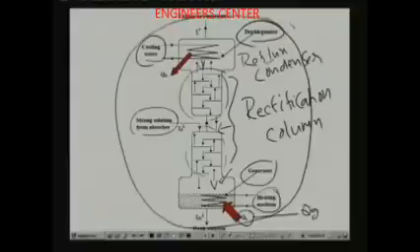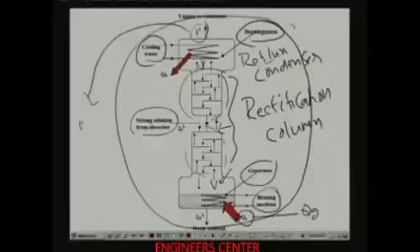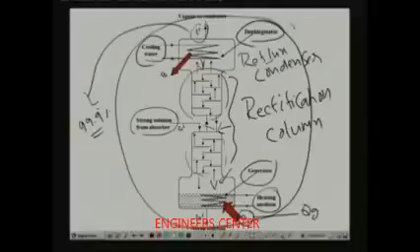That means the descending liquid comes in contact with the ascending vapor, and during this process further enrichment of the vapor takes place. Ultimately, at the exit of the rectification system you have almost pure ammonia. As I already mentioned, you have about 99.9% ammonia in the vapor. In order to achieve this, you have to design the rectifying column properly.